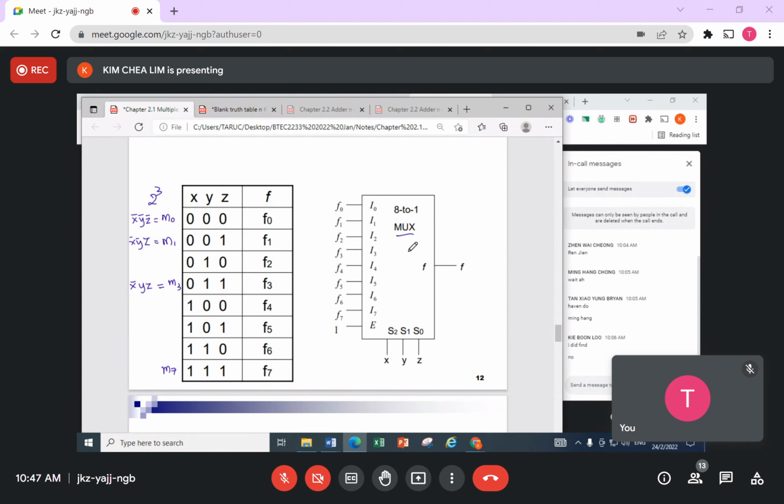But it is a very simple design. What you do here is, this is the input, right? You make it connect to your selectors S2, S1, and S0. When you write your truth table in this form, usually you take this one as the MSB and this as the LSB connection. So the highest is S2, the lowest is S0 in this case.